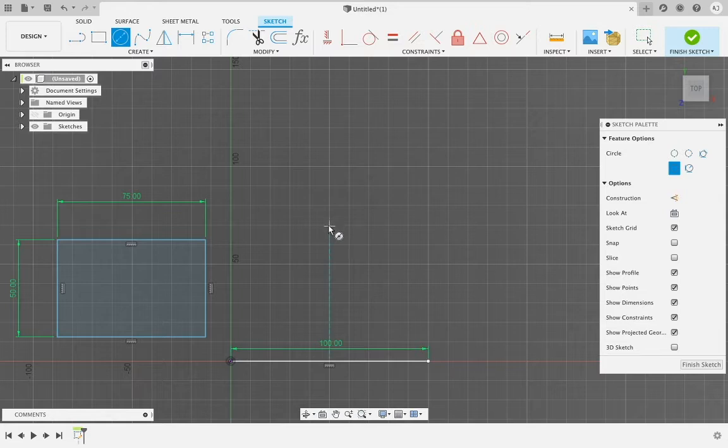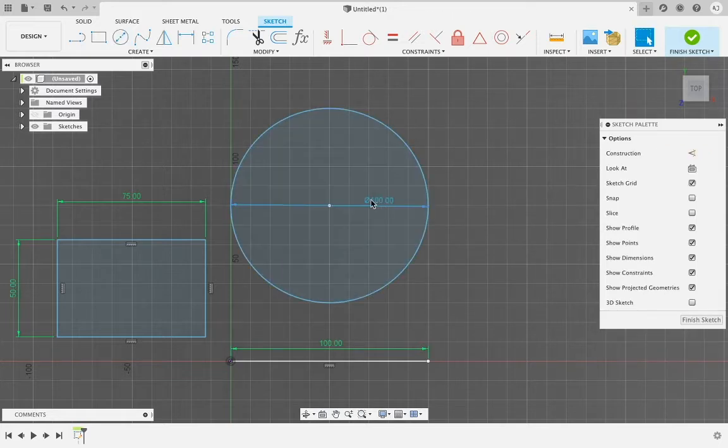Selecting anywhere on the screen, if you want to be at a center point or a coincidence or a midpoint, you can simply press and this will specify its diameter, the length between the left and right side of the circle. We can also punch numbers into this, whether you want 50 millimeters, 5 centimeters, maybe even 10 centimeters, but they're all specifiable easily. Pressing enter will give us this dimension.